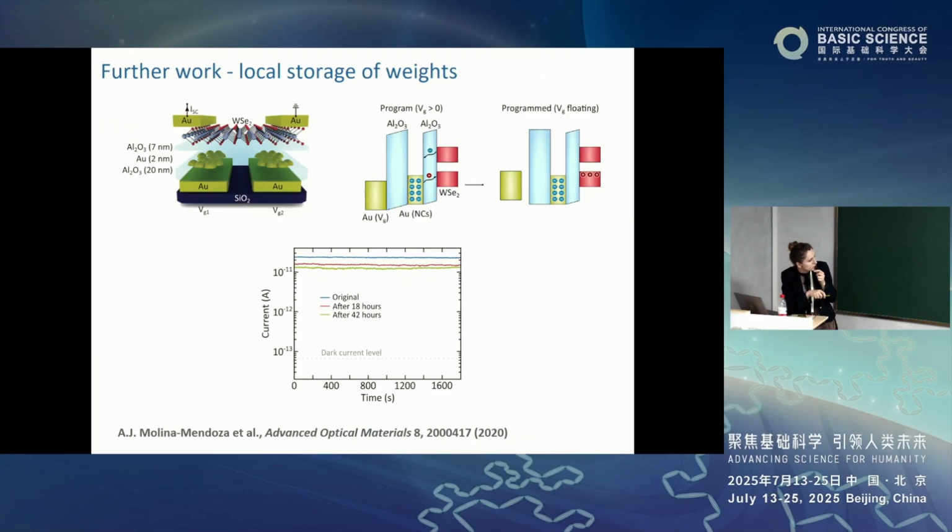So here you have 2 days. I don't know what happened after 2 days. Possibly it died, but it's still quite a lot for memristors. I don't know how familiar you are with memristors, but technically they should last for 10 years, but nobody can really reproduce the 10 years from one device to another. So already 2 days is quite good. It also depends on how you use the sensor. You can use it for an hour and then it's fine, right? Then the proof of concept is already there.